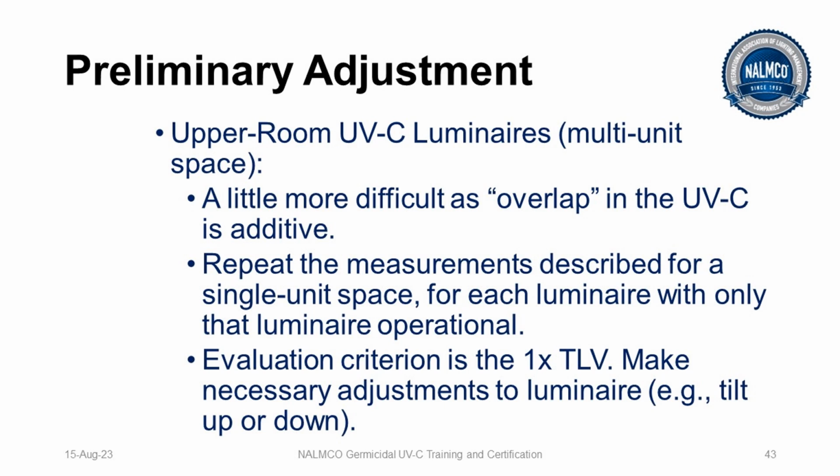Now let's talk about multi-unit spaces. So there's more than one upper room UVC luminaire. It's a little more difficult as the 2 luminaires result in some overlap or some additive effects. What I'll do is repeat the measurements described above for a single unit space for each luminaire with the other luminaires turned off.